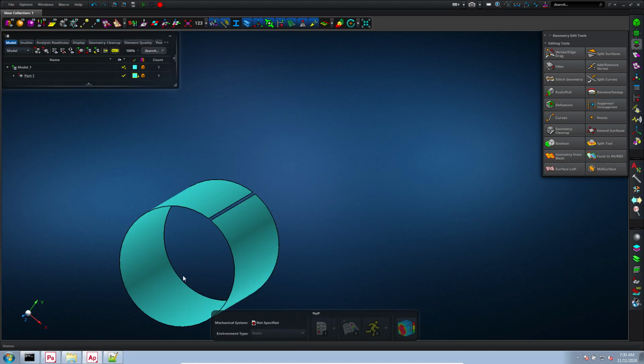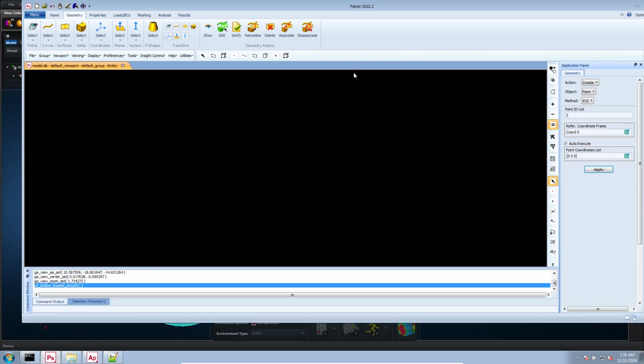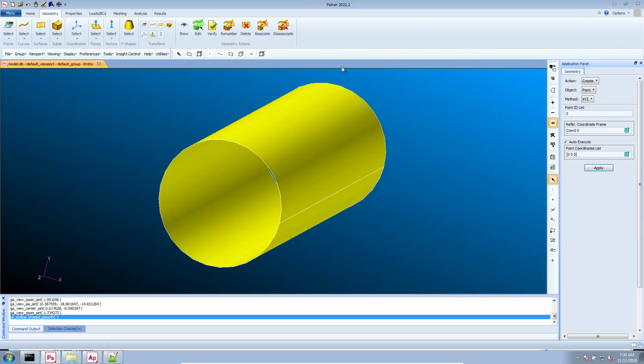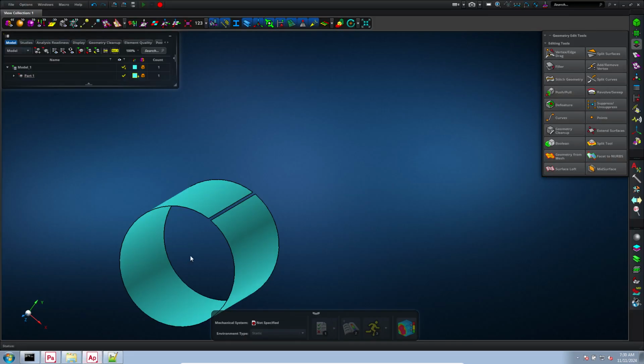You'll find this tool is a lot easier to edit your geometry and to mesh your geometry. After you have your mesh, then you can take it to a tool like Patran and finish configuring your finite element model. You can add your materials, your boundary conditions, and so on and so on. Apex also has some of those capabilities, but it really depends on what your requirements are.